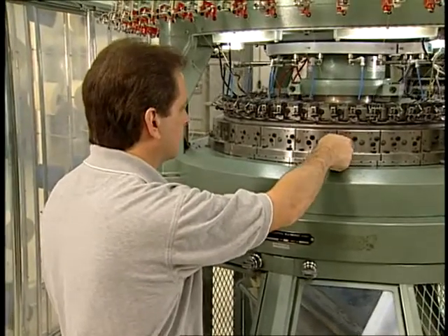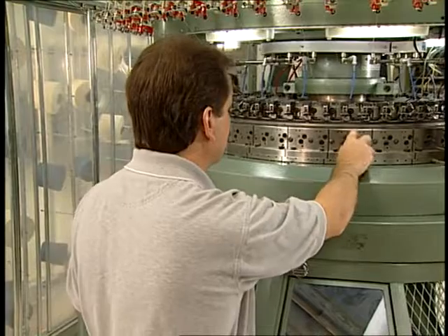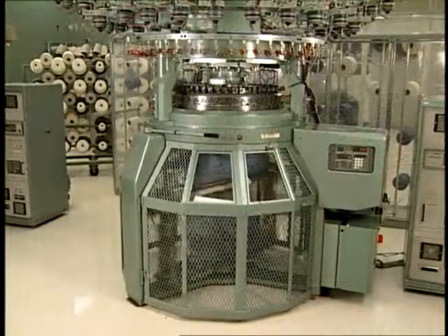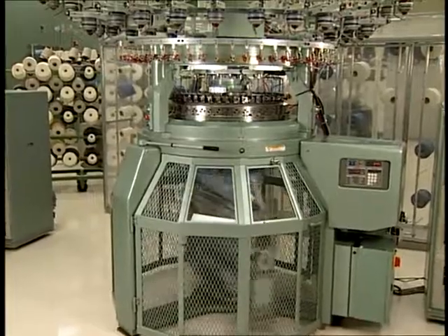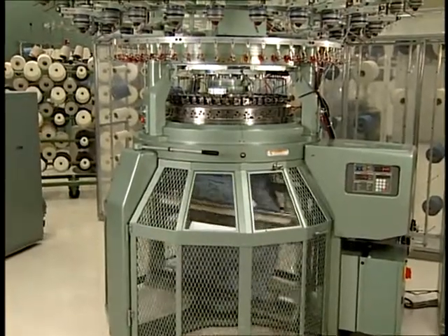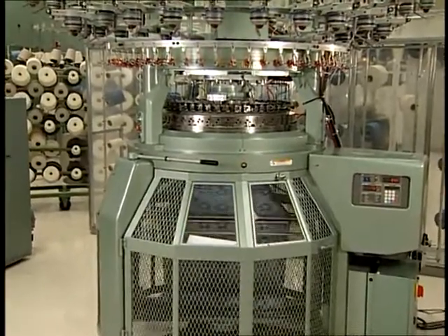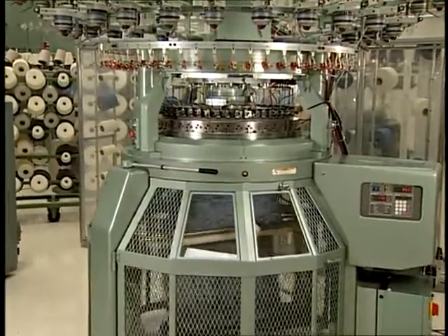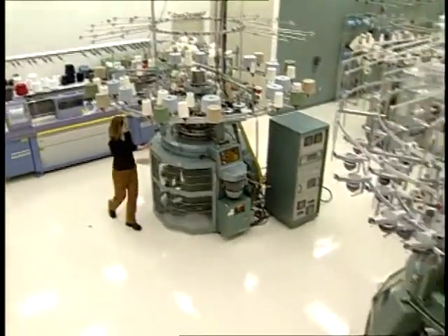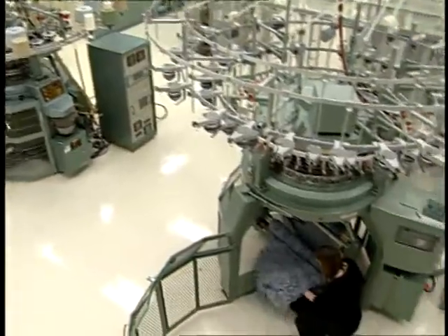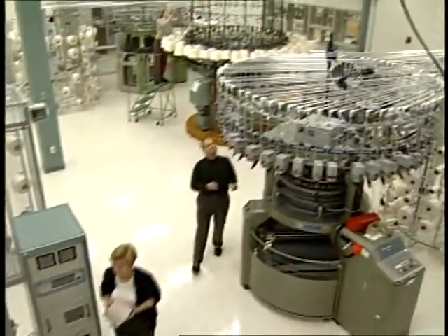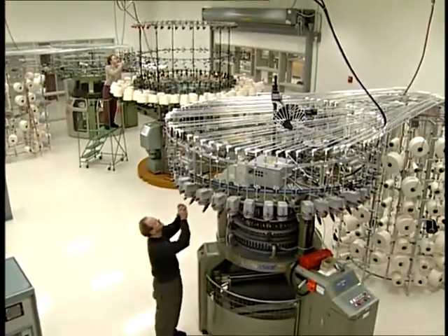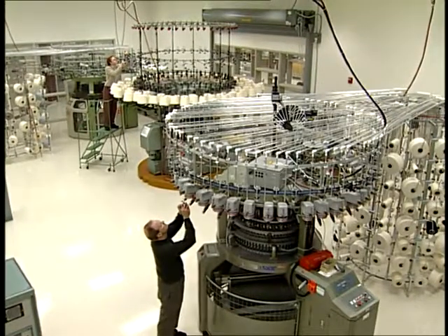In many cases, the customer knows what fabric construction and weight is desired for the product. They may also have a preference for the gauge and yarn size to be used. At the same time, the mill will only have a finite number of these machines and may be limited in diameter and total number of needles. These limitations in machine gauge and diameters, in essence the choice of the number of needles, allow the knitter to choose primarily from only the yarn size and the stitch length as the construction variables.